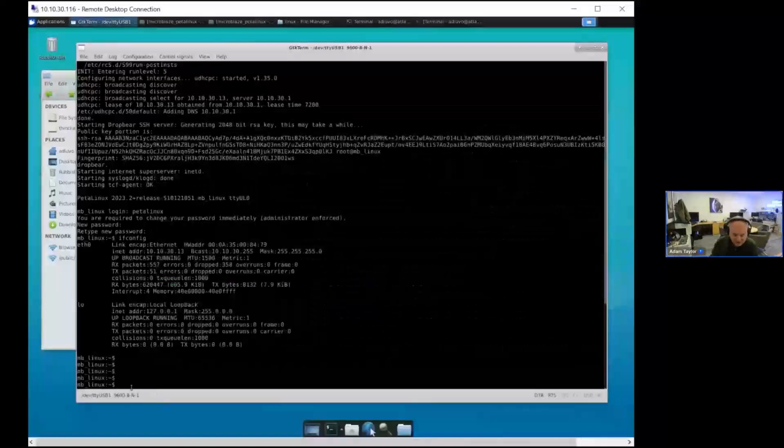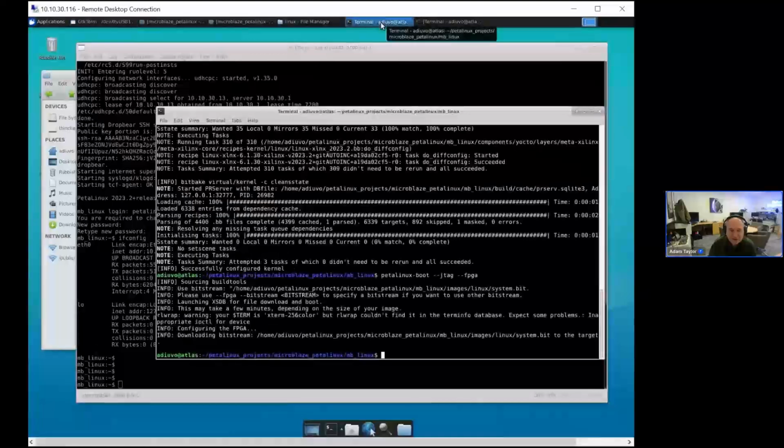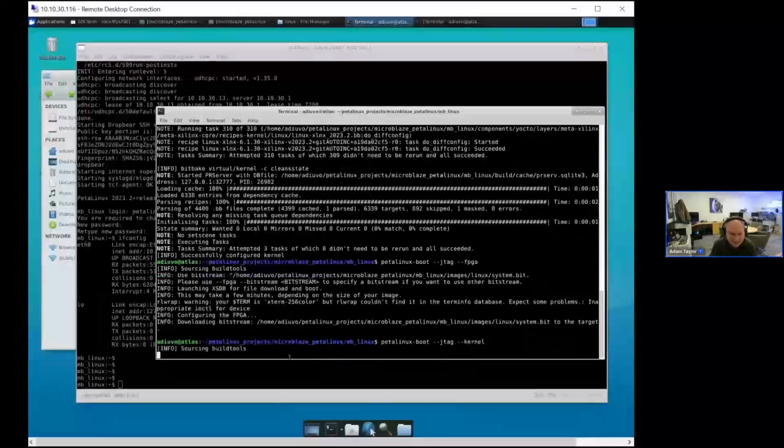We'll see now if I come over to this terminal. Yeah, my terminal's now dead because I'm just reprogramming my FPGA. And that should have reprogrammed the FPGA. And because it's a MicroBlaze, it's blown everything away. What I'm going to do now is I'm going to come over here. Yes, so this step is loading the bitstream into the FPGA. And that bitstream, obviously, in this instance, is loaded in the MicroBlaze processor for the MicroBlaze processor to run. I'm then going to tell it I want to download the kernel and hit enter.